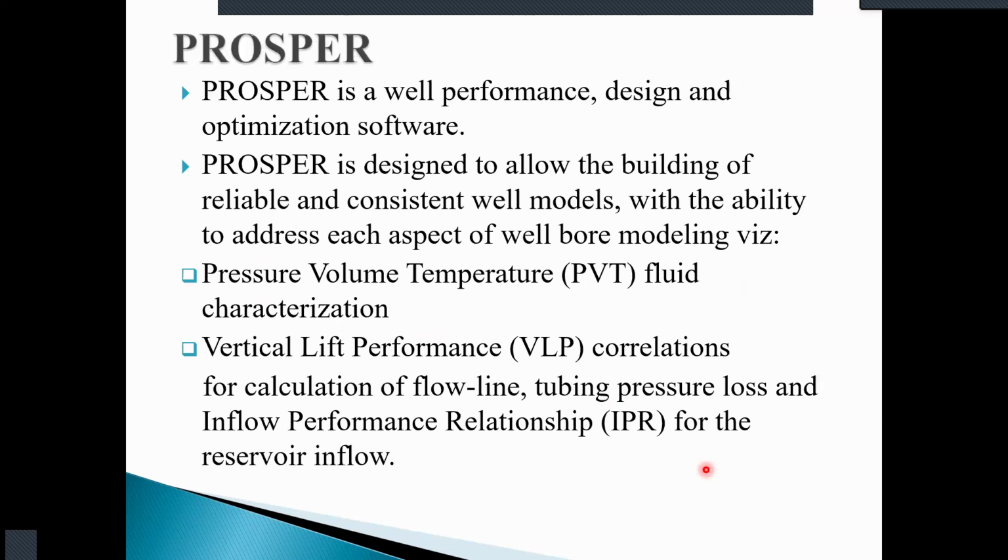So Prosper is chosen. To give you a brief outline about Prosper, Prosper is a well performance design and optimization software. It is designed to allow the building of reliable and consistent well models with the ability to address each aspect of the wellbore, which is PVT characterization, VLP correlations for the calculation of flow line and tubing pressure loss, and the inflow performance relationship. The very basic benefit of simulation software is to match a correlation with the actual production rate happening in our well.